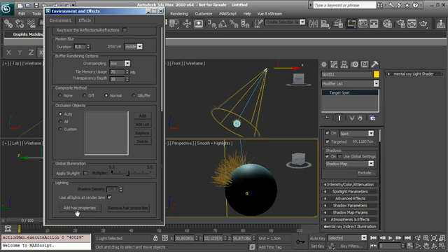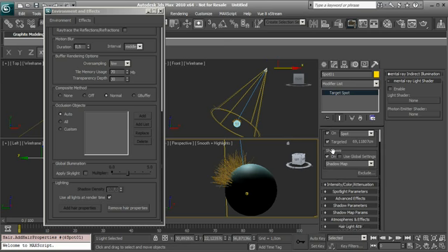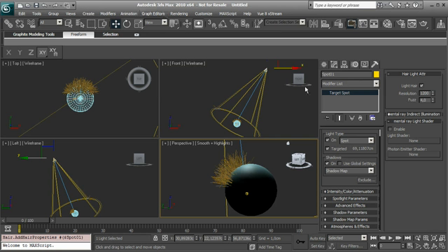Now in the lighting we can set Add Hair Properties to All Lights, and you see that now inside the light we have the Hair Light Attributes, and the parameters are really simple because we have the possibility to set the light on or off here, so this light will illuminate or not our hair inside the scene.